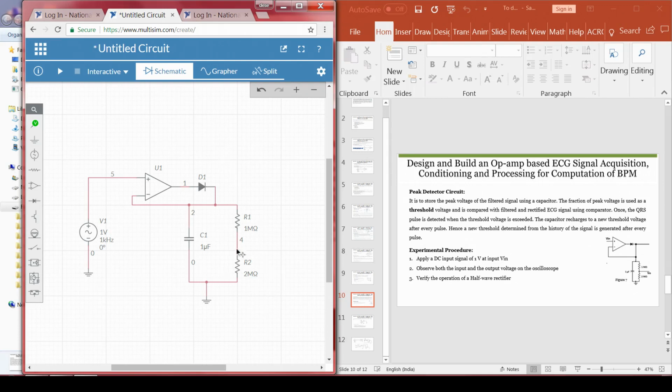What do we have to measure in this circuit? We will see what the output voltage is at this point when I change the input voltage, and whether the capacitor output follows it. In order to understand, let me remove this particular terminal so that there is no connection here. So, we can easily see whether it is following the peak or not. Then we will make this connection, and at this particular node, we connect a probe, and we will see how the output signal looks, right.